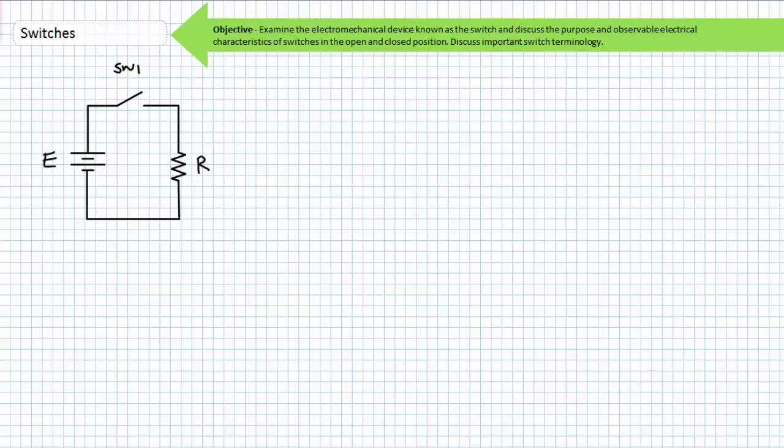At its most basic level, it should come to you as no surprise that an open switch will not allow current flow and that a closed switch will allow current to flow. An open switch is idealized as an infinite resistance through which no current can flow. A closed switch is idealized as a 0 ohm resistance, or short, through which current can flow.